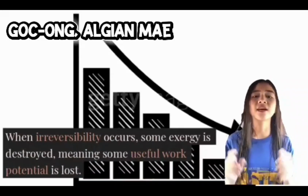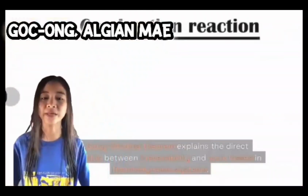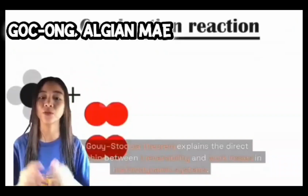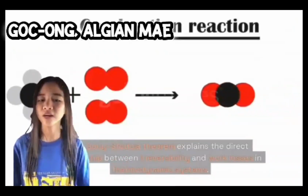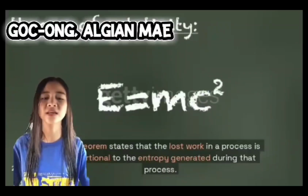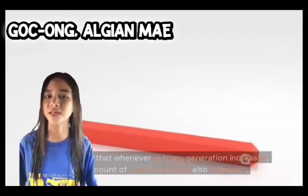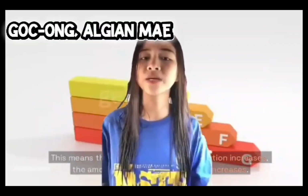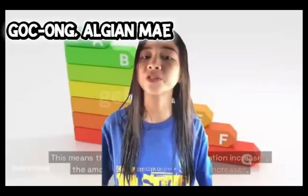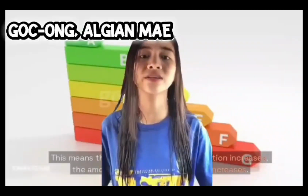Next, let us discuss the Gouy-Stodola theorem. The Gouy-Stodola theorem explains the direct relationship between irreversibility and work losses in thermodynamic systems. The theorem states that the lost work in a process is proportional to the entropy generated during that process. So this means that whenever entropy generation increases, the amount of useful work lost also increases.